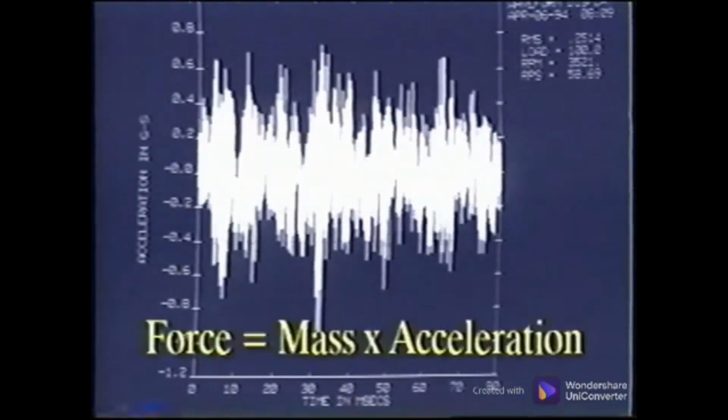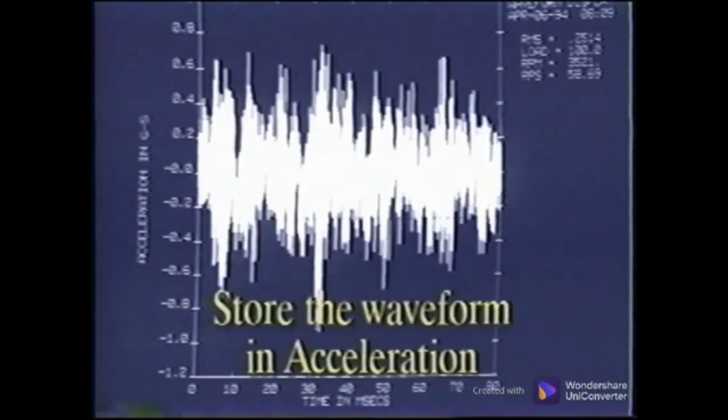point setup. Since acceleration is directly proportional to force, as Newton's second law proves, the energy shown here is related to the force of any impacting that may be occurring in the machine. Since this impacting can be such a destructive force, it is usually best to store and examine the waveform in acceleration units to have the most information.